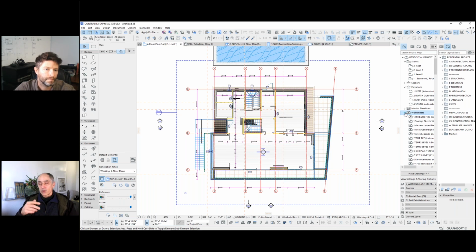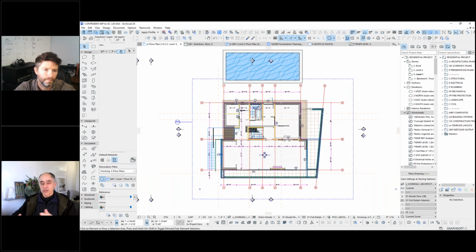When you are doing the ghost image, the trace and reference with a view, ArchiCAD has to think, which layers should I turn on and off? And if it's different than your current view, then it has extra bookkeeping to do because it's turning layers on and off in two different views, trying to keep them in sync. But when you do it from the project map, it basically uses the same layers as your frontmost view.